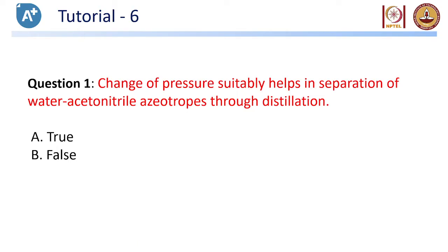Okay, see, essentially we have two kinds of azeotropes: homogeneous azeotrope and heterogeneous azeotrope. What happens in case of heterogeneous azeotrope is you will be able to see two layers of liquids. So using a decanter and the distillation columns, you'll be able to separate it. However, when your system forms a homogeneous azeotrope, what is conventionally followed is